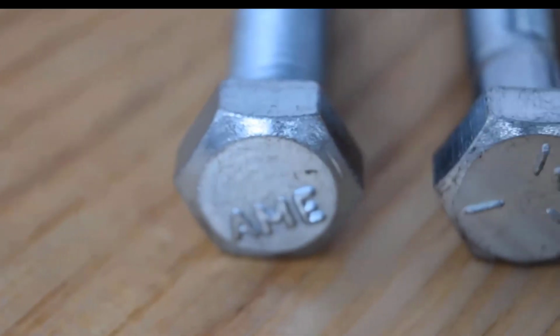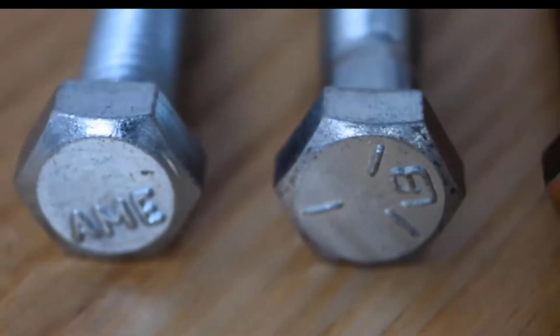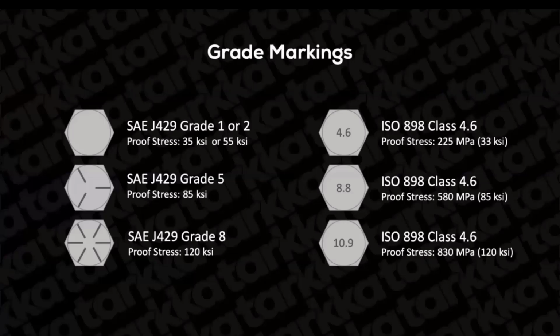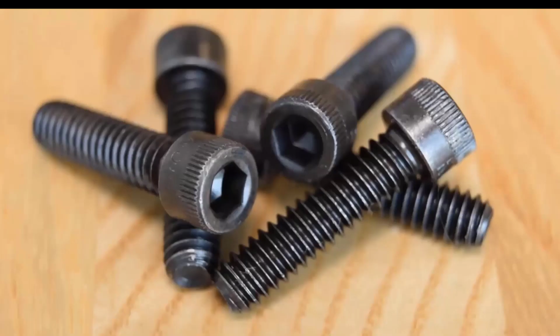Various grades of fasteners are sometimes defined by the standards, and for hex head screws, the grade is usually designated by marks on the heads. Metric fasteners use a system of numbers stamped into the head. In either case, the higher the grade, the higher the tensile strength of the fastener. Alloy steel socket-head cap screws generally have a strength similar to grade 8 bolts.